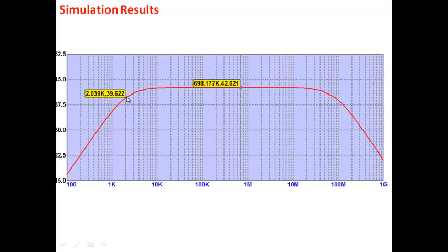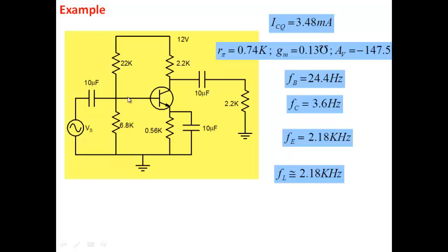Okay. So the procedure is the same for any amplifier circuit. If you want to calculate lower cutoff frequency, it is the same procedure that you have to repeat. Take each capacitor at a time, consider the other capacitors as shorts, determine each one of them, and in the end, if one of them is much larger than the other, that's the cutoff frequency. Otherwise, just sum it up. Just sum it up and you get the approximate value. Okay.